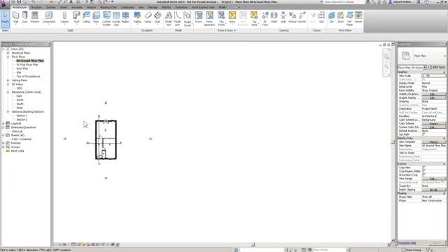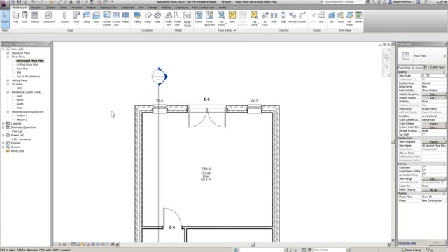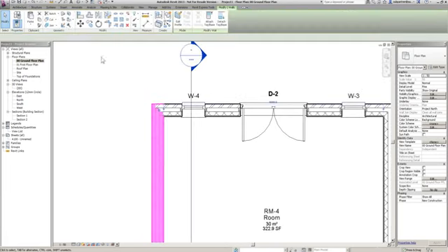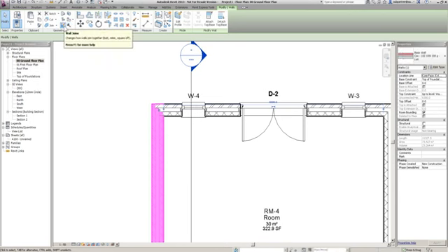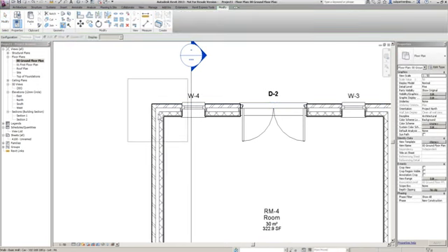In fact, no, I am a little bit too anal about it. So I'm just going to show you how to change that quickly now. Select anything to bring up your modify tools and come over to here where we've got wall joins. When you select a wall join, it will show you how the walls are butting into each other, and they are set to a butt at the minute. We can set it to a mitre, but I actually like to do it properly.